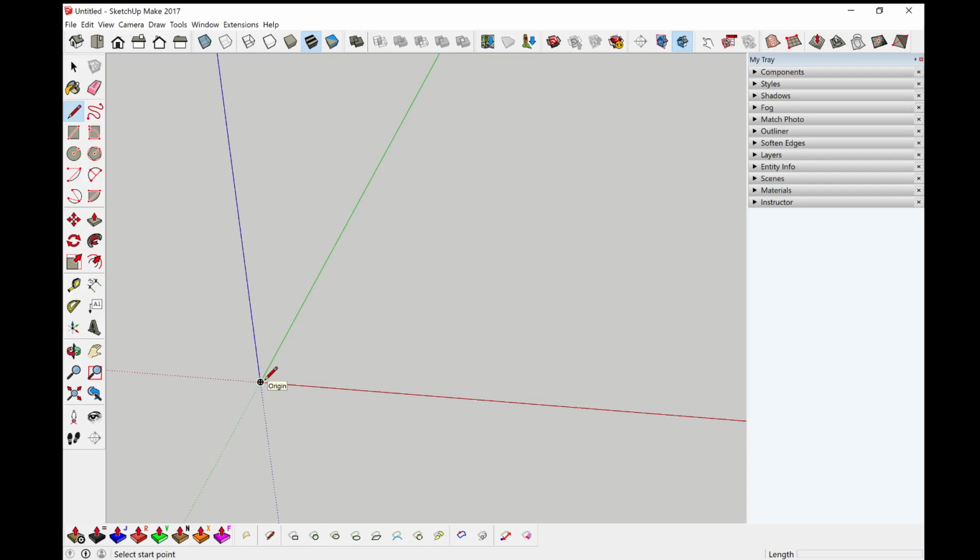Okay, you start out at the point of origin. SketchUp will give you a lot of reference points. Then as you're moving, if you hold on to shift, your line will become bold. That means wherever you move, you'll be stuck. So let's say if we want to go for 5000 mm, you see the measurement bar has changed. Then you press enter.